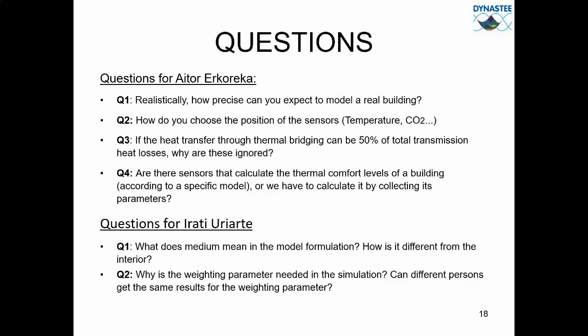Then there are also parameters related to air quality, such as the CO2 concentration, that gives you very good information about the ventilation system in that thermal zone. If the ventilation is not enough, the CO2 concentrations will be too high.